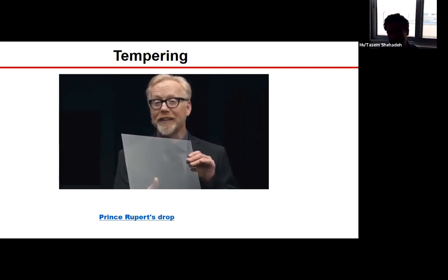In terms of simulating the behavior of the solid sample after it has solidified, after it has undergone the rapid cooling, this can be simulated using either particle methods, maybe finite element, in which fracture, XFEM, extended finite element, in which crack propagation can also be included, can be used to simulate such behavior.